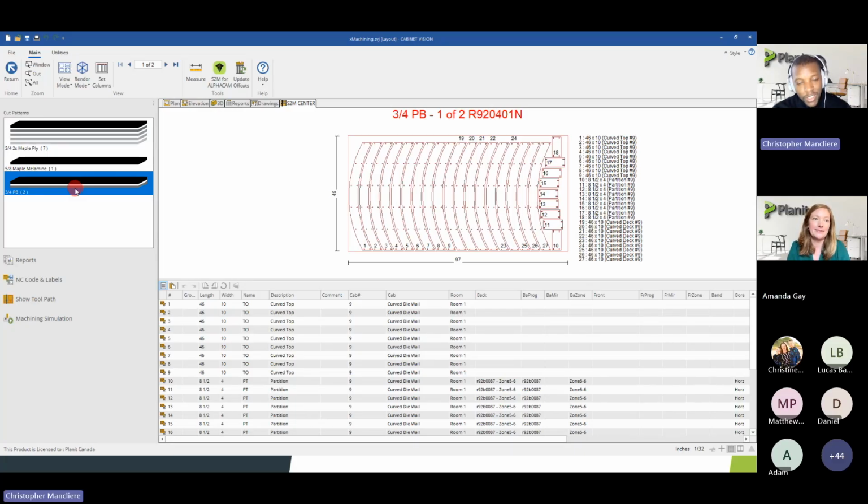Very good question. At the moment, no, unfortunately. The TrueShape will actually try to find a matching position across the entire sheet. And you're right that the numbering will be much less easy to follow along than block nesting. And that's really one of the reasons sometimes if you don't need TrueShape, maybe don't use it all the time, if you know it's mostly blocked, like let's say rectangular parts. But no, there's no way to renumber or actually force the number to be moved to a specific position.